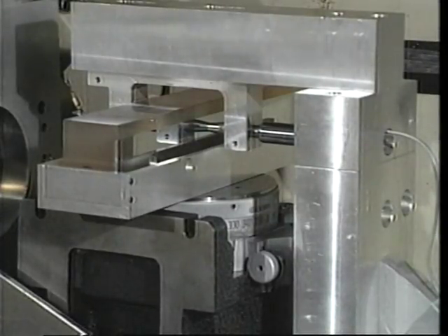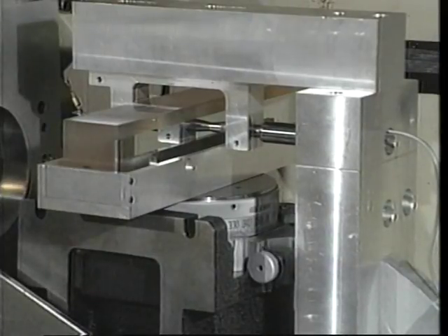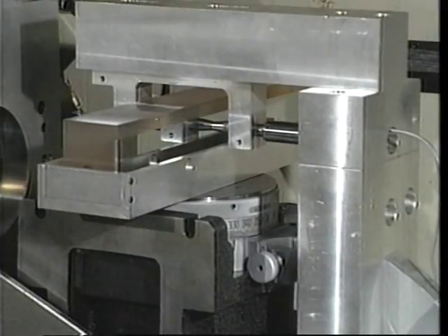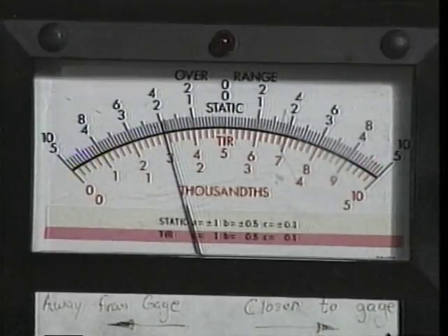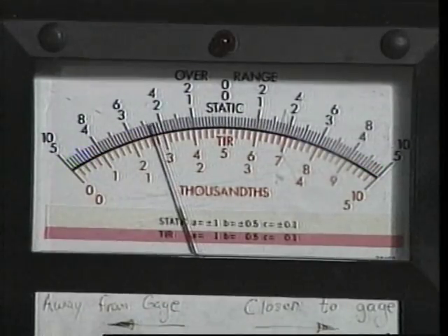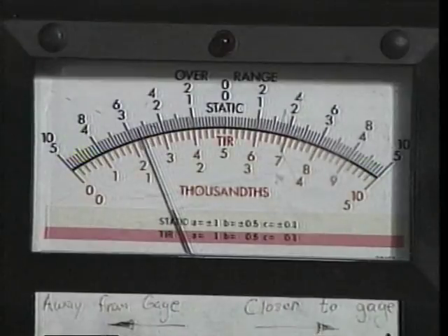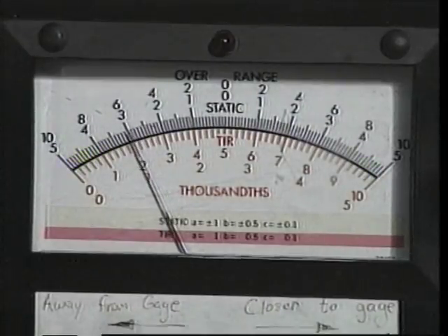Next, the x-axis slide is jogged so that the cap gauge probe is traversed along the straight edge away from the center of the index. The change in the separation of the probe and straight edge is monitored as the probe traverses until the cap gauge reading goes off scale or the x-axis end of travel is reached.